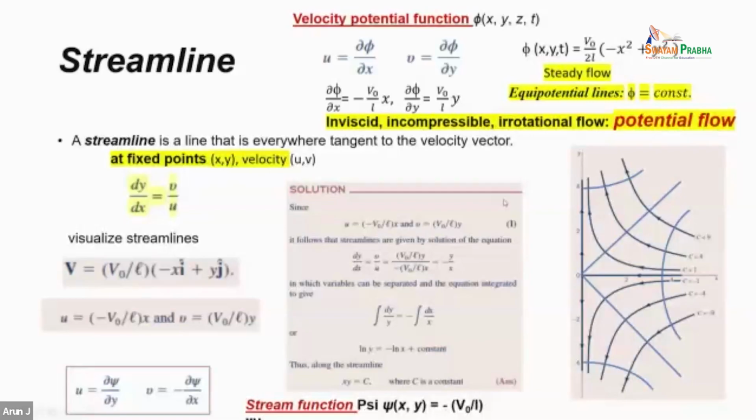In commercial software, like ANSYS, there are different packages, ANSYS Fluent and ANSYS Aqua. ANSYS Aqua solves the potential flow function, and in that kind of case, you don't care about viscosity. It's just the potential flow. In wave energy converters, one way to solve that is WAMIT.